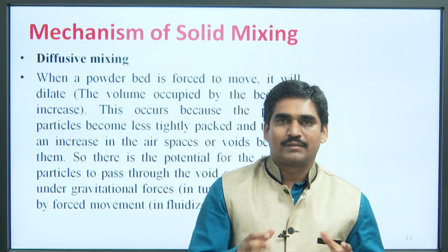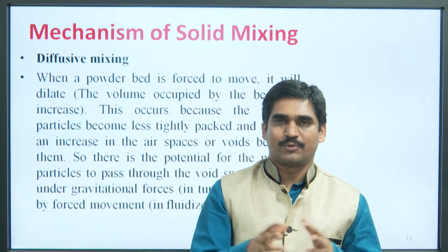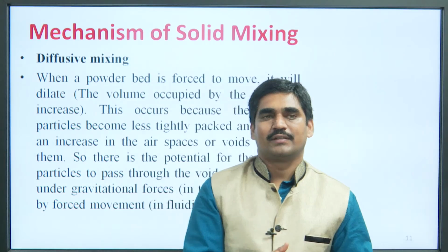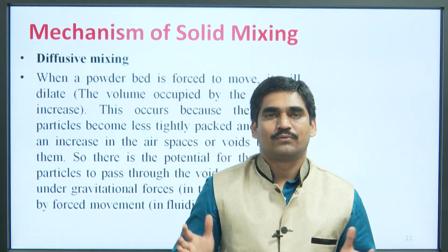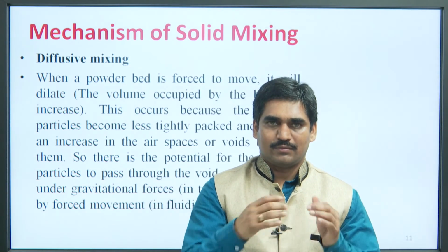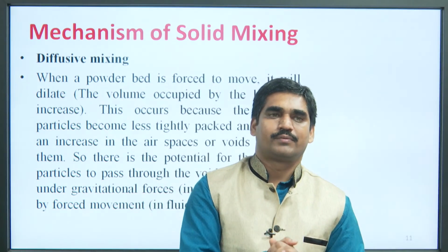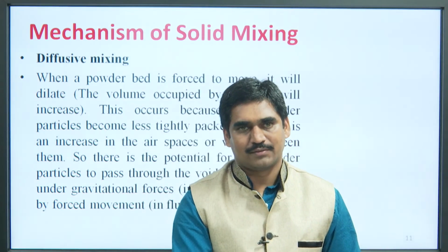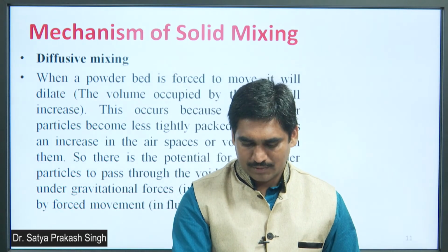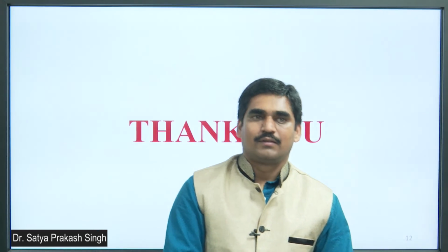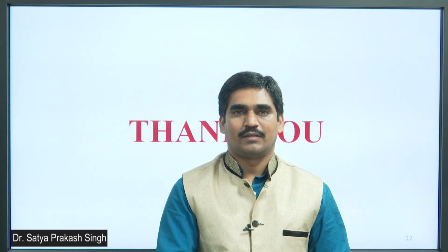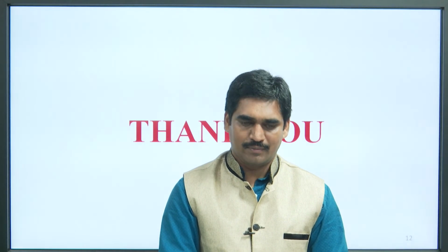So, there is a potential for the powder particles to pass through these void spaces under gravitational forces, as in case of a tumbling mixer, or by forced movement in a fluidized bed. This type of mixing is known as diffusive mixing. In a fluidized bed or in a tumbler mixer, the diffusive mechanism is followed. These are the basics of different mechanisms of solid mixing and differences between solid mixing and liquid mixing. Thank you.